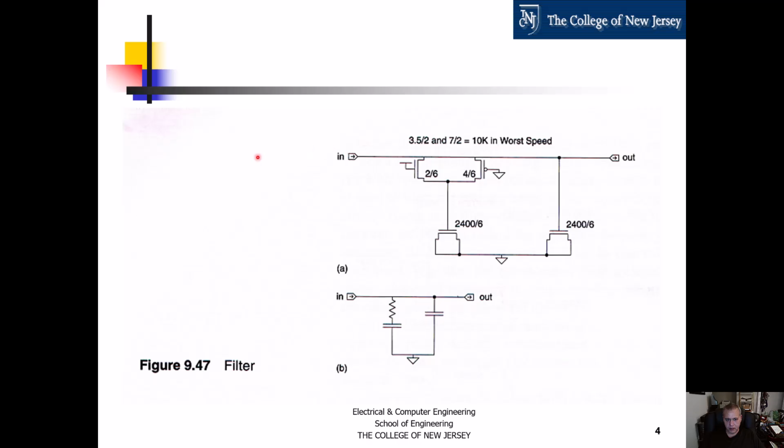And remember, when you are inputting a current in or out, inputting a current or extracting charge, a current coming out of this network, what you get respectively are voltage ramps up or down. If you're putting current in, you get voltage ramping up, which is the integral of that current pulse. And if you get a negative current pulse, so getting charge out of the network, you get a ramp down, which is the integral of that negative current pulse. So this is the output of the filter that goes into the voltage controlled oscillator.